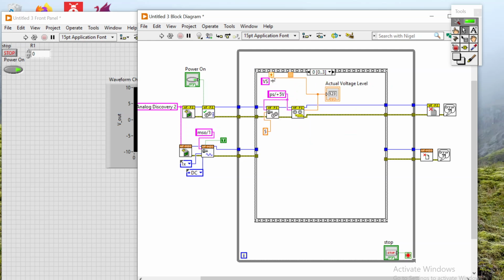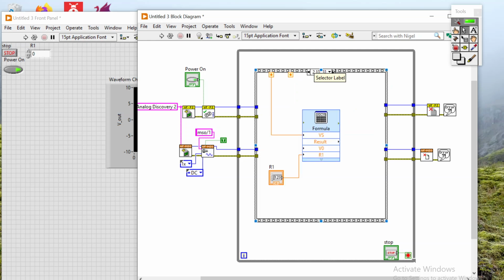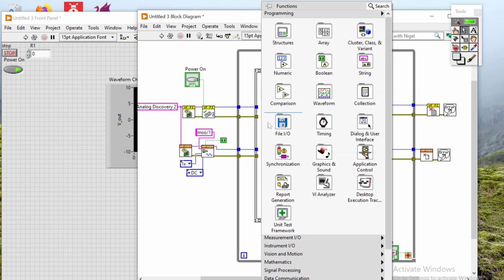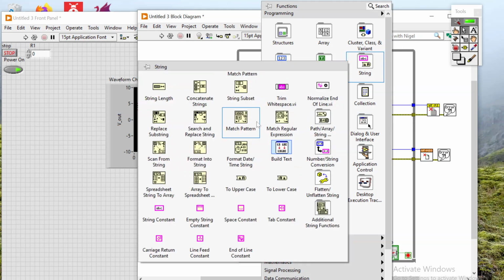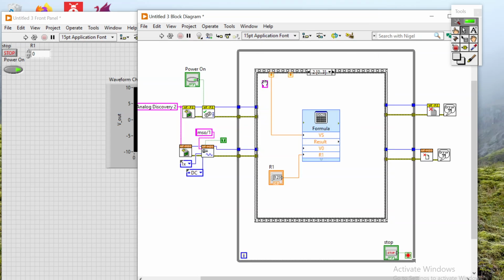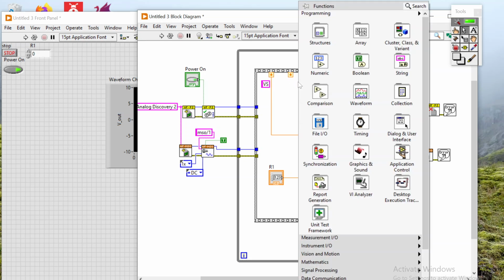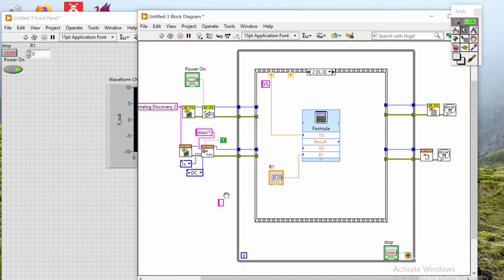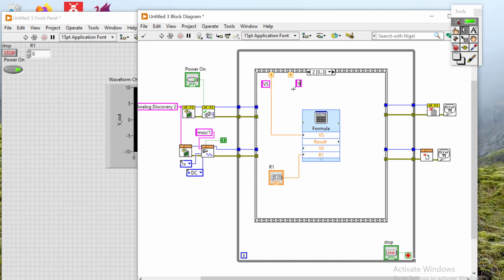Notice too, Vs is coming out of here, but I can't have V out come into here because it only passes things to the next scene. So okay, now let's do another string so we know what we have here. This is Vs. String. This is V out. And so I'm going to wire this V out here. And now I just have my result.